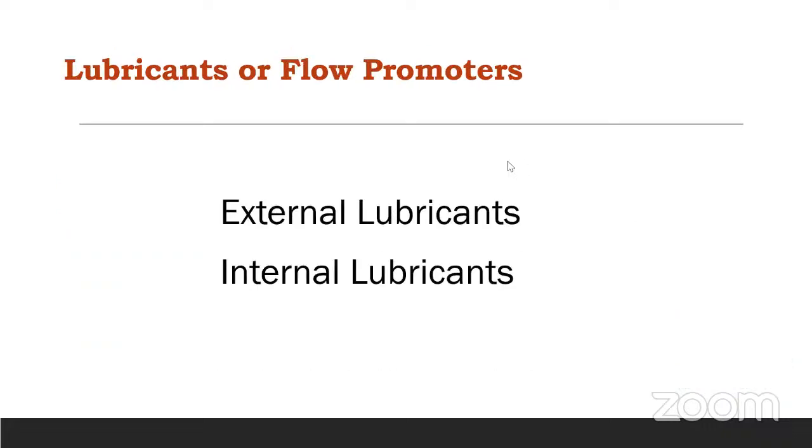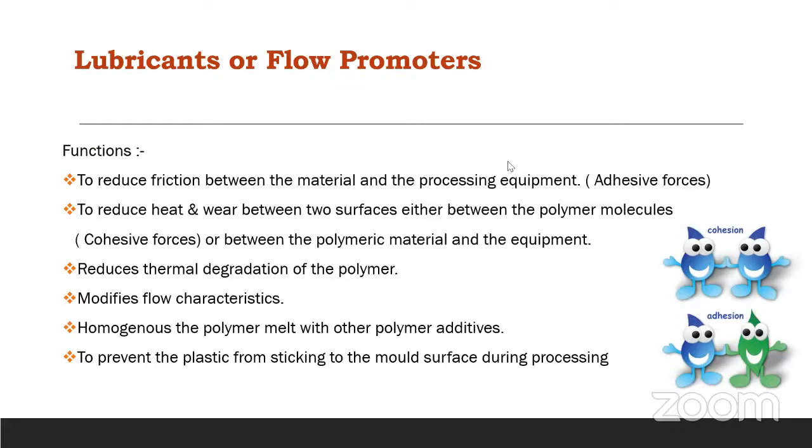Sir, will there be any reaction, like in polyvinyl chloride or benzene, when there is chain opening, when you add the additives? There will not be any reaction. These additives generally act on a physical level. There are different polymer chains, and the additives interact with them, but this interaction is physical, not chemical.